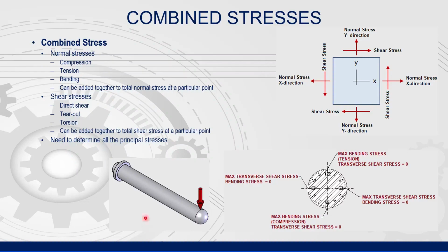Generally, there are two locations on the beam where we need to consider the applied stresses and create stress elements for those locations. Consider the cantilever beam shown here. If we take a cross-section at the point of maximum stress, there are a few key locations to consider. I have superimposed a clock face on the cross-section to help identify these locations. One stress element should be taken for either the 12 o'clock or 6 o'clock position. These locations are where the bending stress is maximum for this setup.